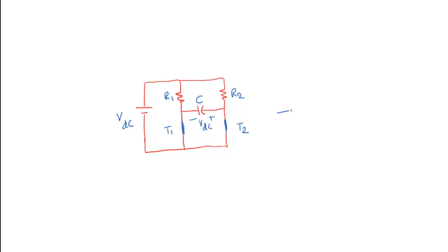So thyristor T1 is already connected like this, which is in conduction. But at the time of turning on the thyristor T2, this is the meaning. Here T2 is turned on, means this will act as a short circuit. That means this potential point and this potential point are the same. Then this capacitor will be connected across T1 like this. If the capacitor is connected across the conducting thyristor T1 like this, it will act as a voltage source.